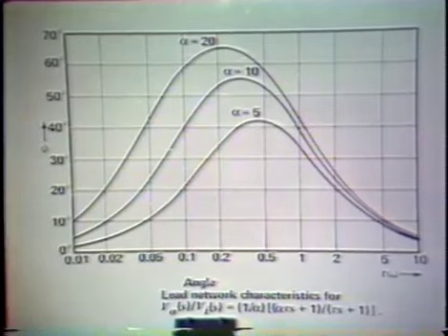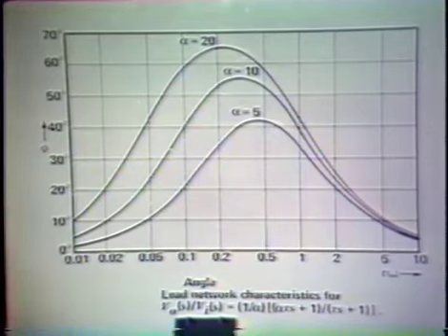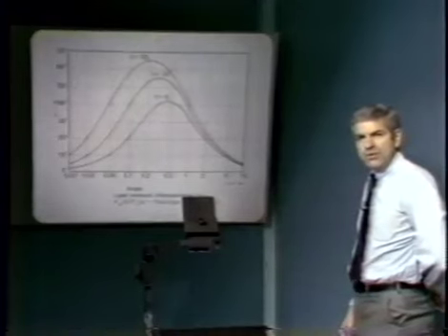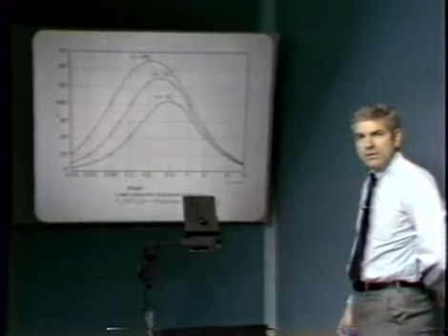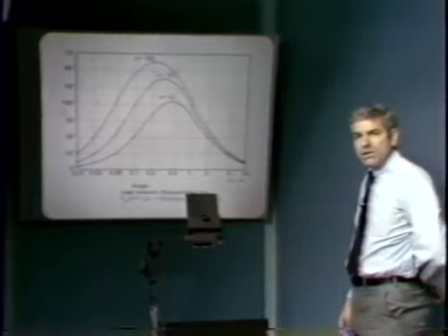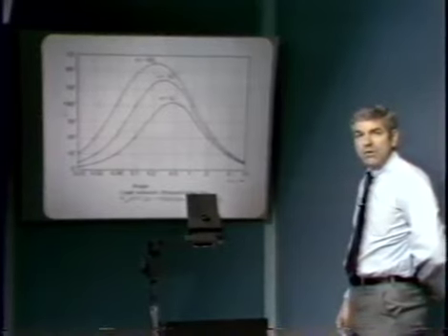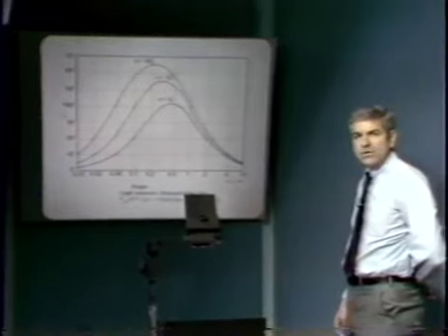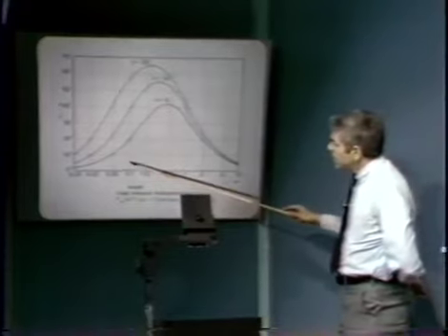The important thing that we exploit in this sort of transfer function, or at least one of the things that we frequently exploit to improve the performance of a feedback system, is that we begin to get positive phase shift before we have made an appreciable change in the magnitude characteristics. If we look at our angle curve, we notice that there's appreciable positive phase shift out of all three of the characteristics shown at the location of the 0.